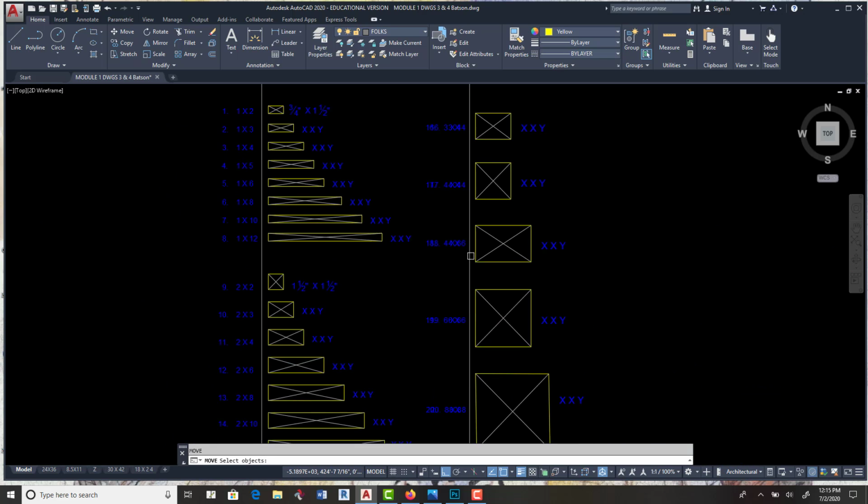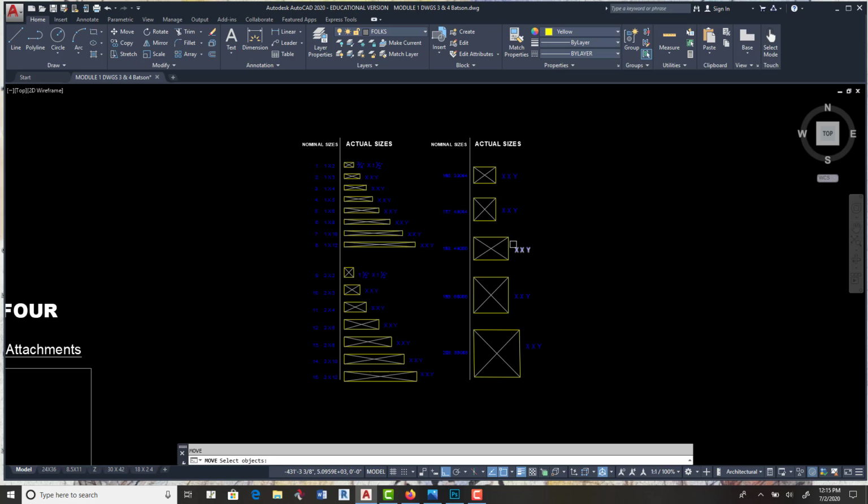So this is the command that makes drawings out of just files, not blocks. Blocks are within drawings. Blocks don't transcend other drawings. So if you open up another drawing, these blocks will not be in it unless you save it to your prototype and you open your prototype. So blocks are only in the drawing that you create. The W block becomes a permanent DWG file, just like the other files that you open. So the command is escape, make sure you have a blank command, W block, enter.